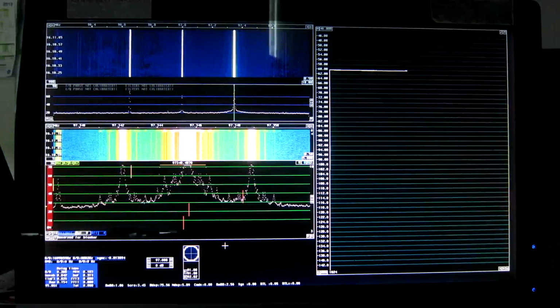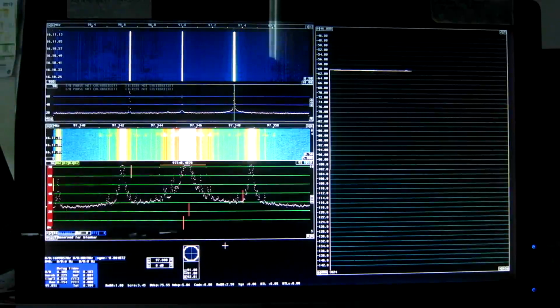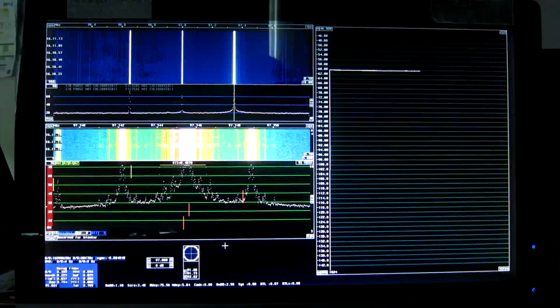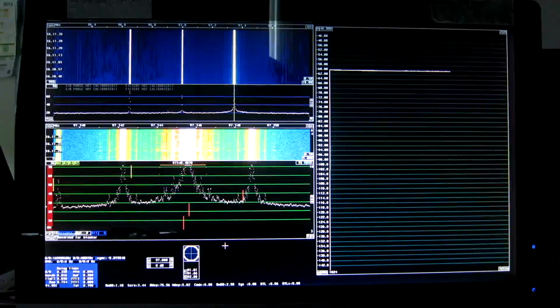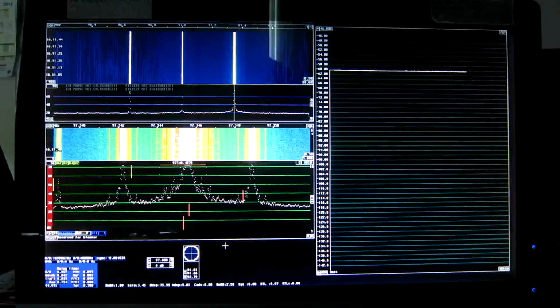Now I have lowered the sampling frequency to 1.7 megahertz and also applied a better window for the first FFT. This is the sine to power 3 window. There are still spurs caused by inadequacies of the window function. They would go down in level if I would set the bandwidth smaller, but that wouldn't fit the cache of this old processor.